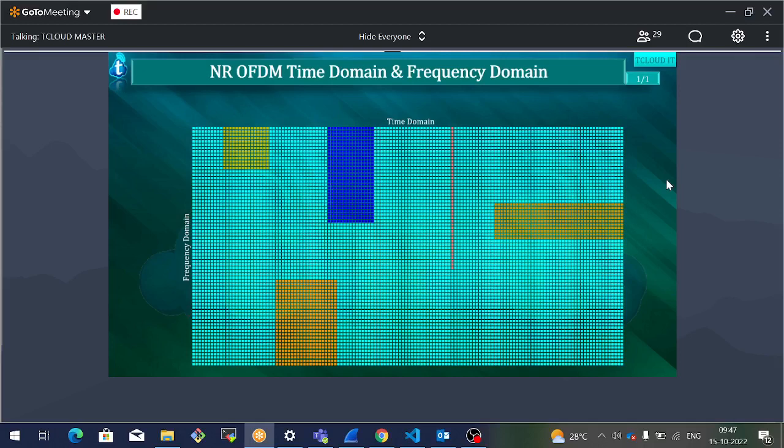So what is a mobile supposed to do when it comes up? It'll have to perform something called synchronization. Find out what's going on, where exactly it is switched on. For example, if you have the time domain divisions, let us suppose one frame, subframe, slot, etc., the mobile needs to find out where it is. All these frame and all this information, it needs to find out.